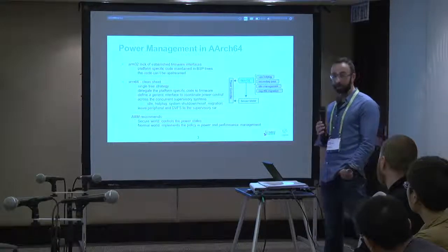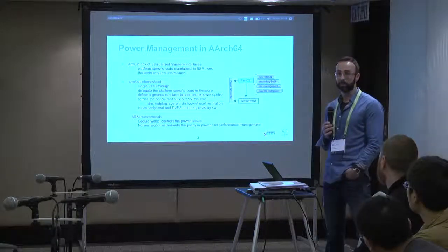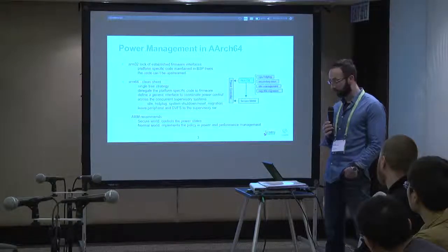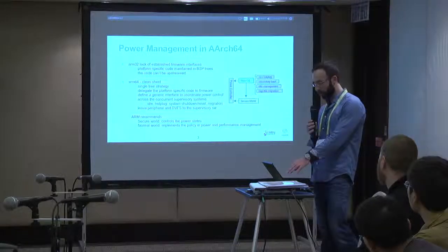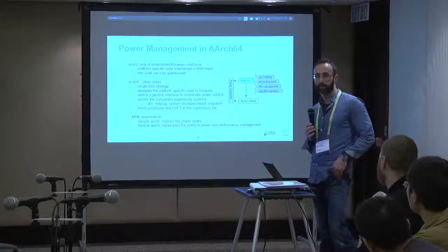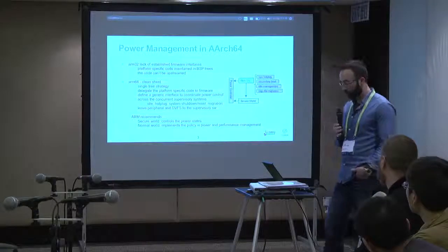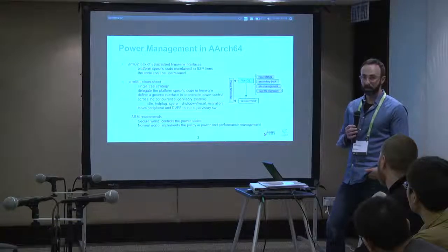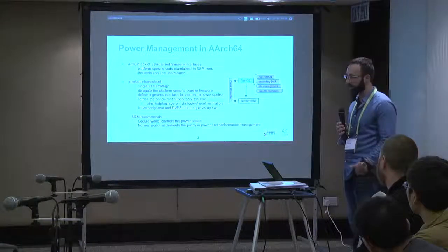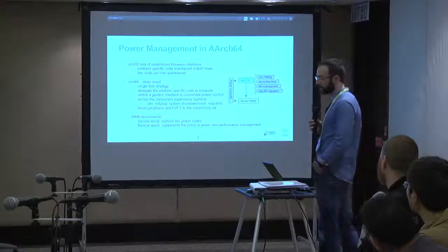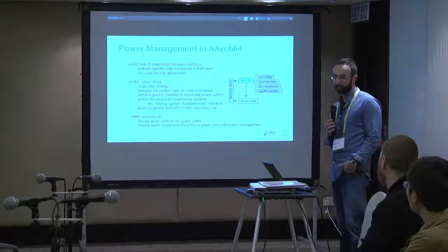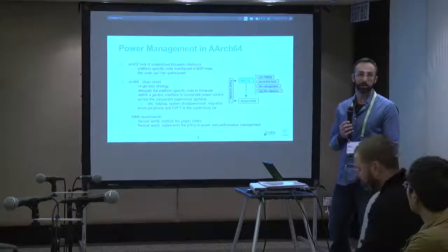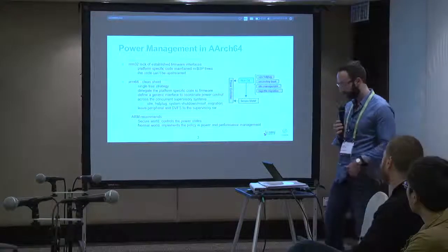Again, PSCI is very clear on what it wants to cover. The secure world is going to control the power states for the CPU. The normal world is going to implement the policy and all the performance management. PSCI doesn't contemplate devices, and things like frequency scaling are also not contemplated by the spec.